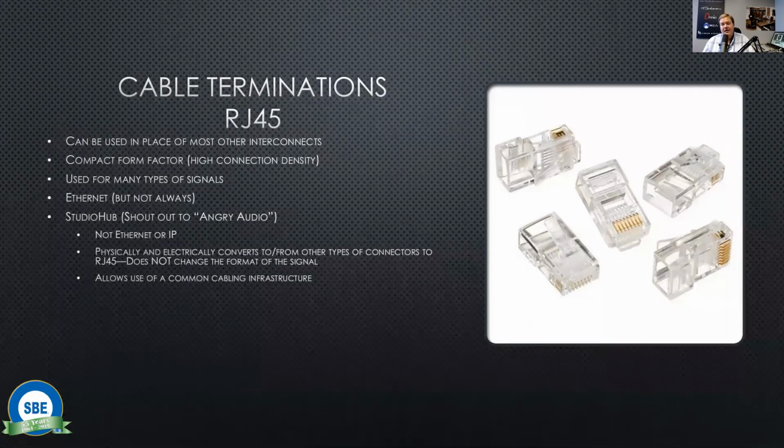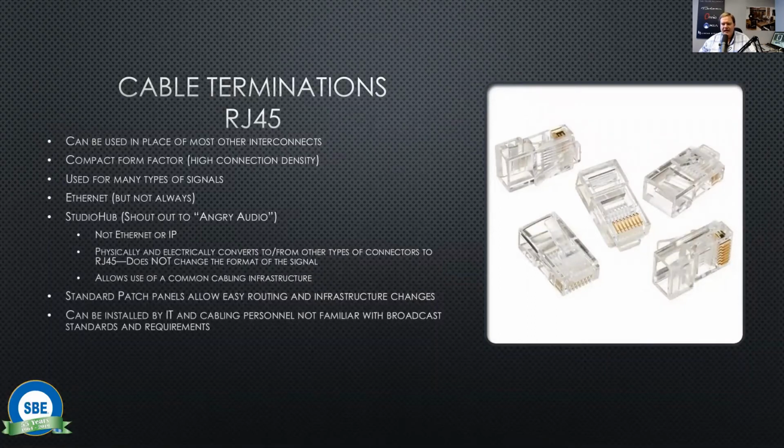It does allow use of a common cabling infrastructure. So if you've got Cat5 or Cat6 cable run all over your facility already, this might make some sense. Standard patch panels allow for easy routing and infrastructure changes. It can be installed by IT and cabling personnel who may not be familiar with broadcast standards and requirements. You wouldn't expect a structured cabling guy to come in and start soldering XLR or TRS connectors, for instance. But you do want to make sure you're using the right connectors with the right cable. There are cables for stranded, there are cables for solid, there are cables for Cat5, there are cables for Cat6. Just make sure you're using the right connectors and the right termination tool for those connectors with the right cable.